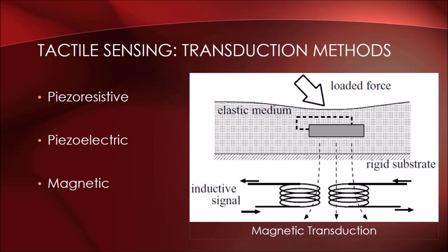The piezoelectric sensors work on a principle that a voltage is generated when a material such as certain crystals and ceramics is distorted. The voltage generated is directly related to the applied force. These sensors exhibit a very high frequency response, making them an ideal choice for measuring vibrations.